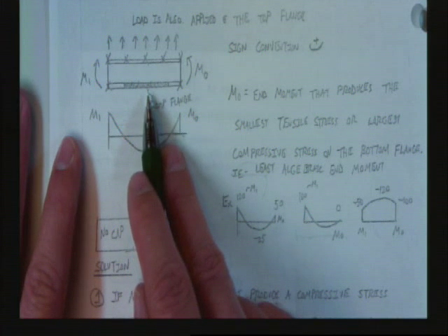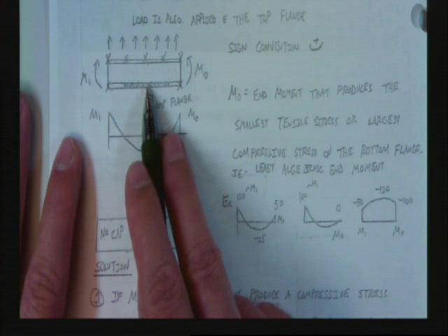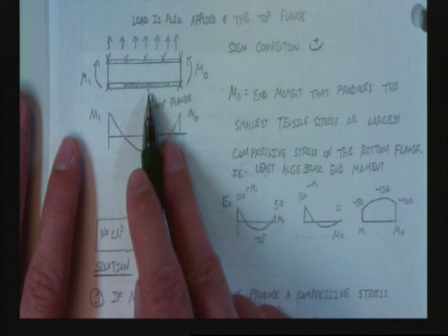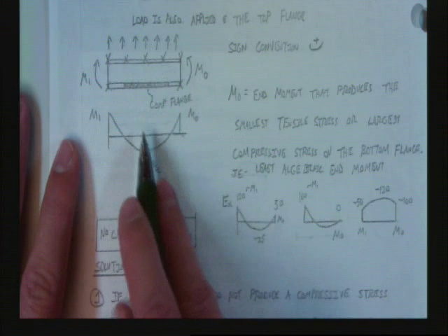Instead of cutting, what if you put a brace? Where would you want your brace to go? On the bottom flange. The top and the bottom. And that's why you'll notice when a brace is done correctly, if you brace the top and bottom flange, you don't have anything to worry about. You're good. It's a brace. Right? It's only when you brace just one flange that you start to run into some problems with this.